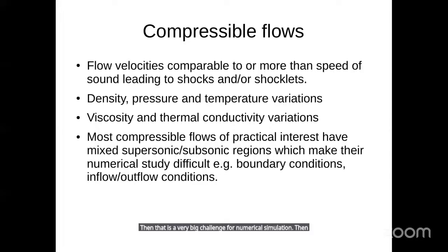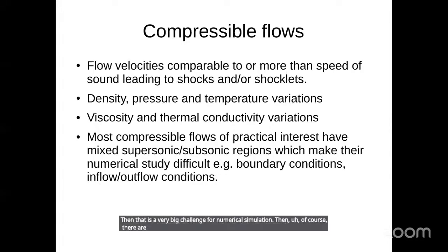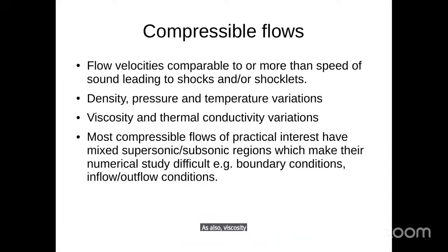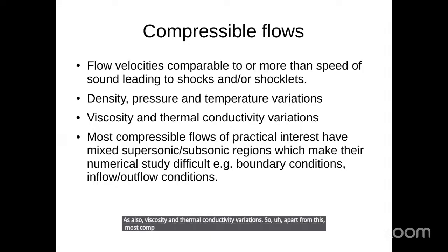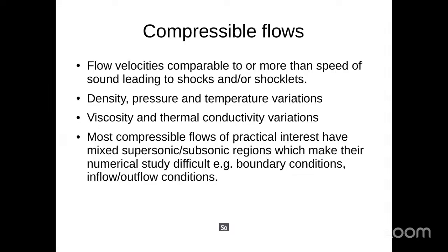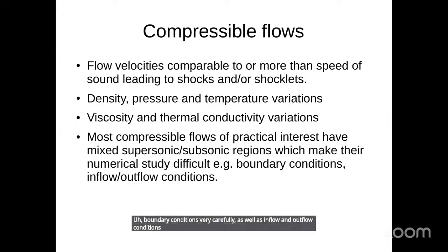Then of course there are density, pressure and temperature variations all happening simultaneously in such a flow, as also viscosity and thermal conductivity variations. Apart from this, most compressible flows of practical interest have mixed supersonic and subsonic regions, which make the numerical study difficult. That means you have to specify boundary conditions very carefully, as well as inflow and outflow conditions. During the talk I will elaborate more.